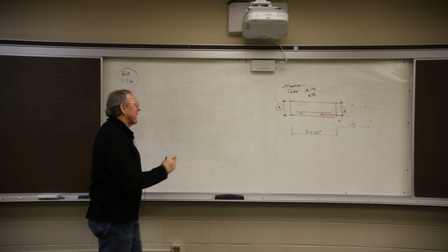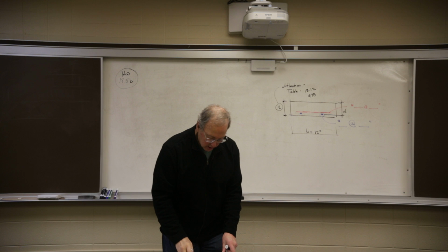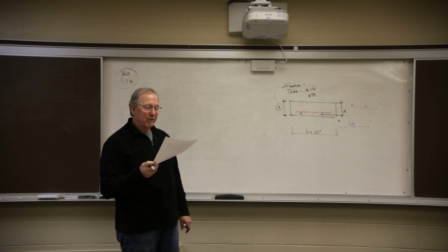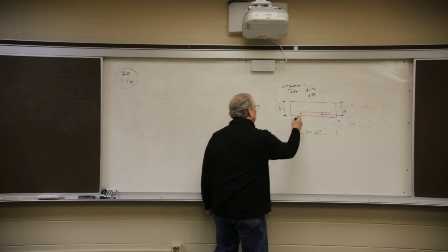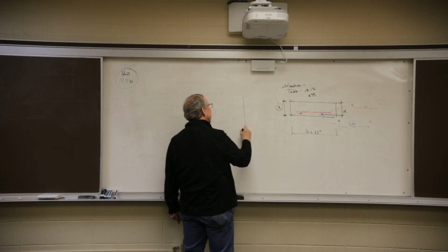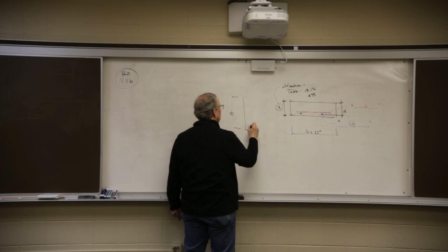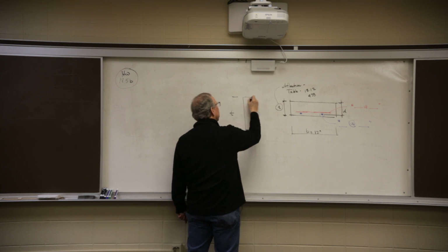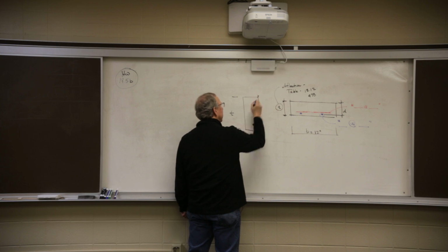So if I take a look at this cross section and I take a look at the requirements, and if you go through the requirements, it's going to tell you that the cover for a slab is 3/4 of an inch. So if I looked at this and I looked at the difference between T and D, T is the thickness of the slab. There's the main bar right there. Okay, so D is the dimension from the top of the slab to the center of the bar.